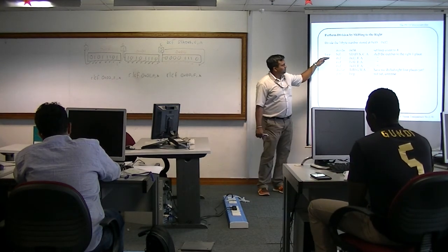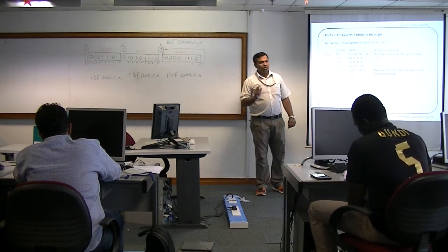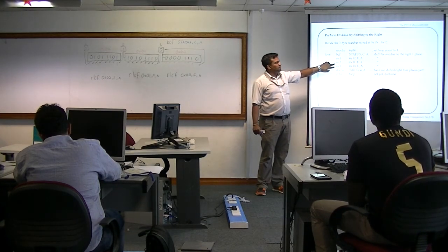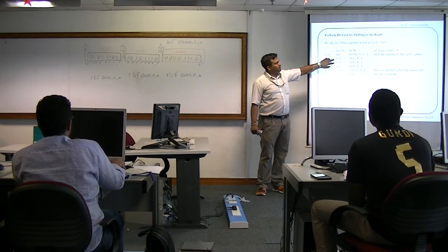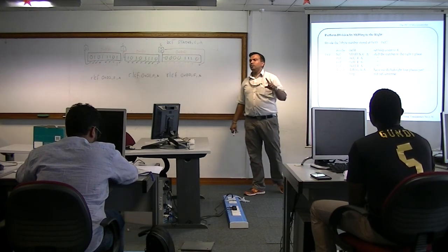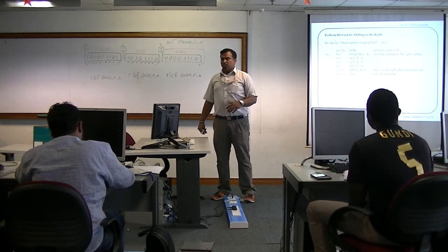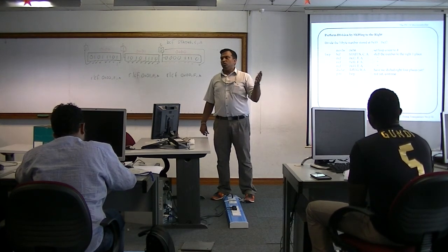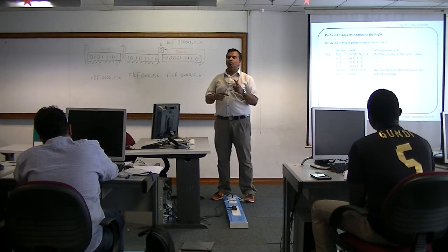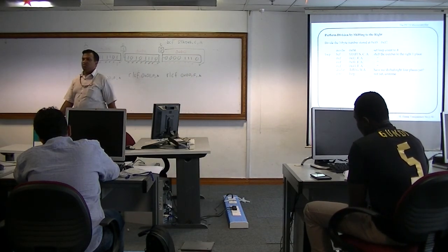If we have 4 times looping, it means divide by 16. So take note, if it's a 3-byte number you'll have 3 instructions. If you have a 2-byte number you only have 2. If you have a 4-byte number you'll have 4 instructions. The number of loops determines the value that you want to divide or multiply by. Do you understand? If you're just going to multiply by 2, no need for a loop. Just one time is enough. If you want to multiply by 4, then you just loop it 2 times. You understand? So with that, we are done with chapter 2.